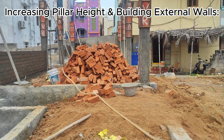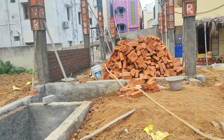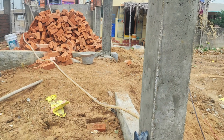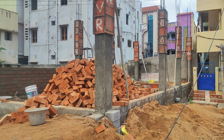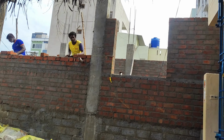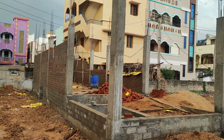Increasing pillar height and building external walls. After completing the base structure, the next step is to increase the height of the concrete pillars to reach the slab level. Once the pillars are extended and properly cured, external walls are constructed using bricks according to the approved building plan. These walls shape the structure and define the external outline of the house.